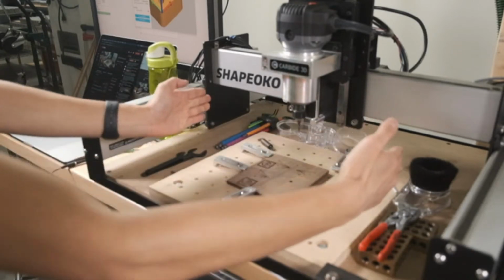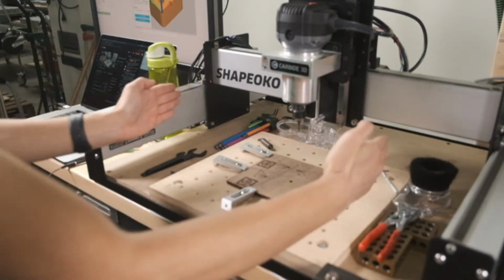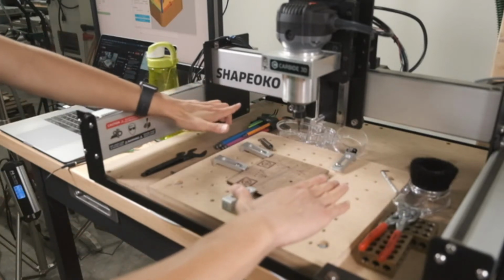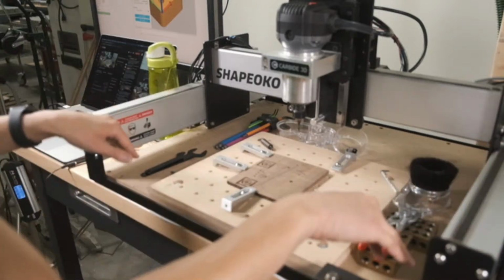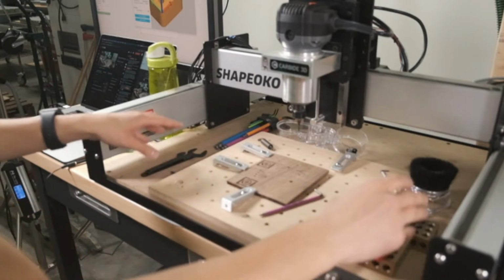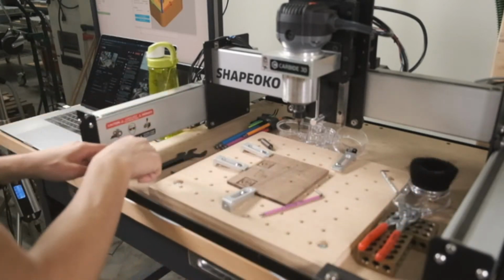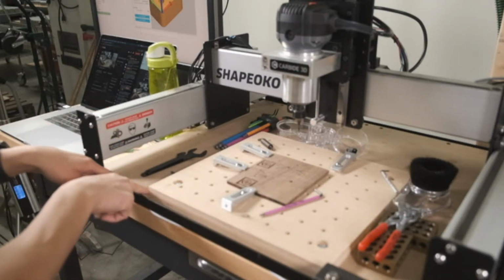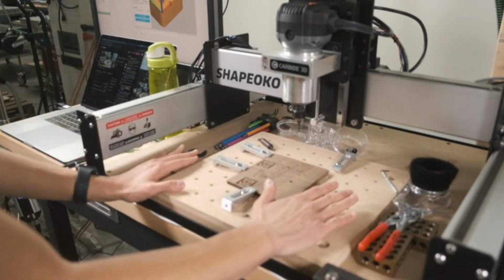If you think about these two Y-axis rails, there's not a lot keeping them from doing this, from turning the whole machine into a parallelogram. By locking these two into the MDF, the skin tension of this MDF keeps the frame from doing this. So for people who want to forego the MDF, you have to make sure that you're not compromising the structural rigidity and squareness of the machine.